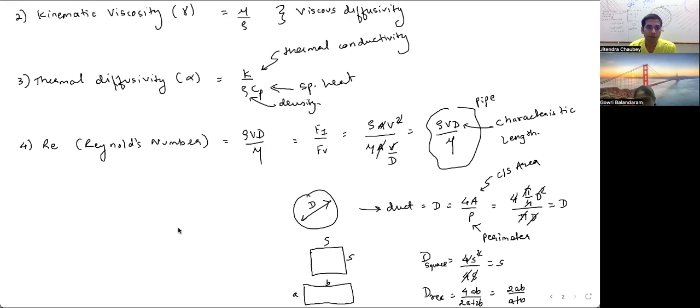If we are talking about internal flow, like these are all internal flows, if it is pipe or duct, it is called internal flow. For internal flow, for pipe or duct, if the Reynolds number is less than 2000 or sometimes 2300, the flow is considered laminar.